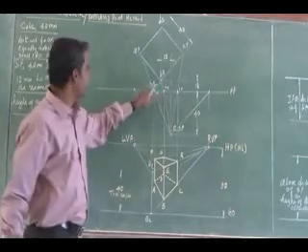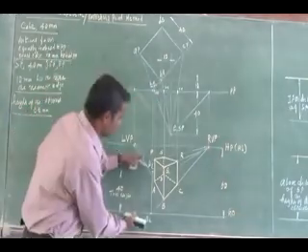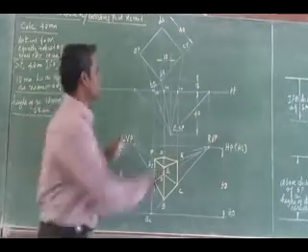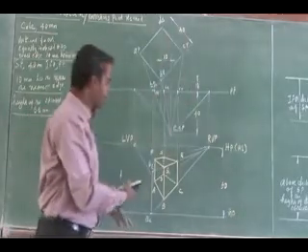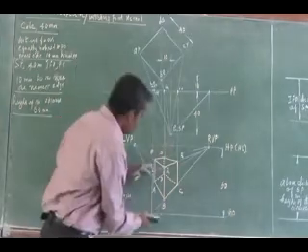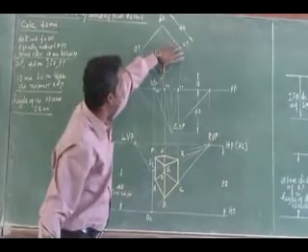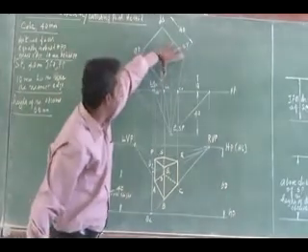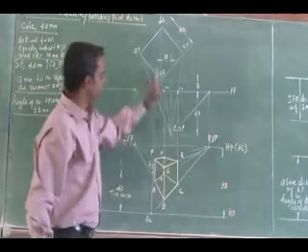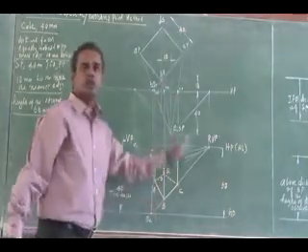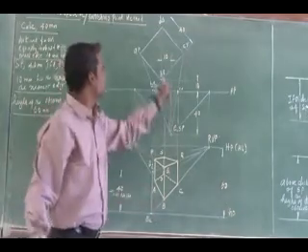Since it is not touching, I have extended to obtain the true height B2 Q2. Since I have extended to the left side, parallel to the right vanishing line, then I have joined to the right vanishing point to obtain the perspective of this face BQ and CR. So intercept as usual, by the previous method, I have got the perspective face of this one.